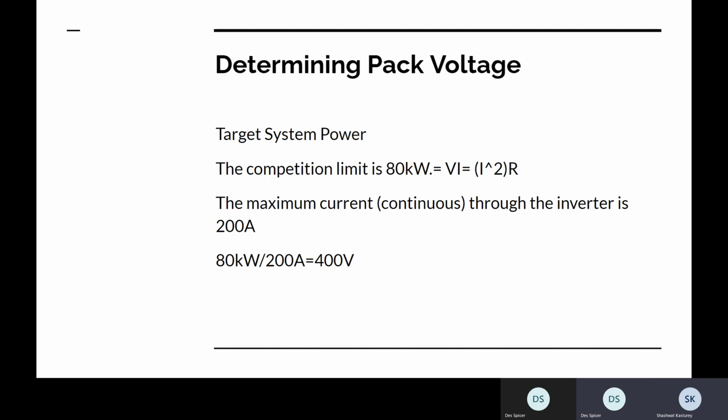So, like I said before, right quick, to actually give you the answer on how we got the capacity of the battery pack, the energy. That was a calculation from what we could actually draw from the battery. So we actually did battery testing about 1.5 years ago. Well, actually, no, it's close to 2 years now. And what we got from that battery testing was that we could only pull about 20.75 amp hours from the cells between the ranges that we actually wanted to use them in, which is about 4 volts to 3 volts.